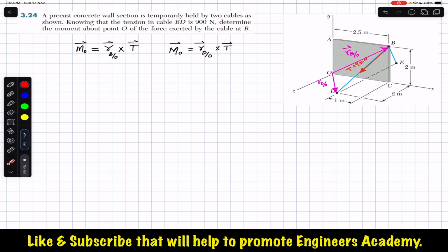So to evaluate this equation, we need to have this tension T as a Cartesian vector, and we need to have this position vector as a Cartesian vector. So we need to write these in terms of i, j, and k, and we need to write the tension T in terms of i, j, and k. We are going to solve this problem by using two methods. So this is method number one, by applying the cross product method.